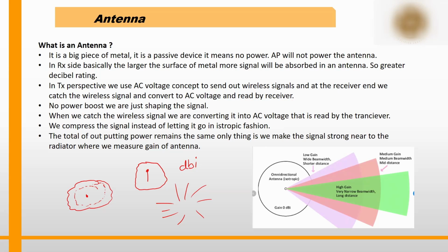An actual side-by-side comparison of antennas requires you to walk around the cell that this antenna builds. Suppose it's an isotropic cell. You need to walk with an RF meter, take numerous signal measurements, then plot the measurements on a piece of paper.